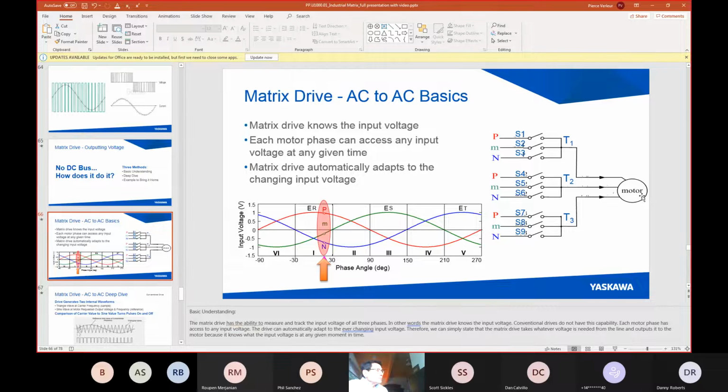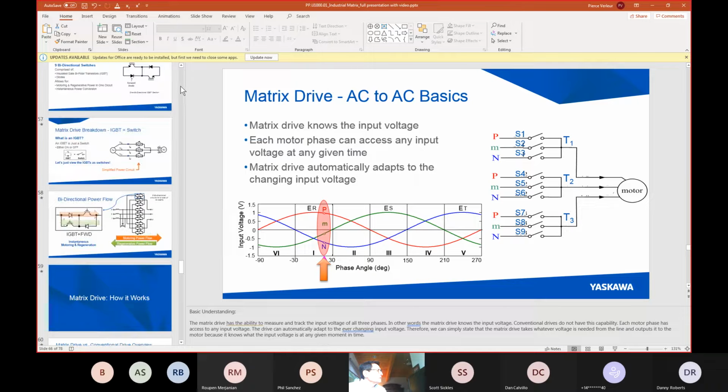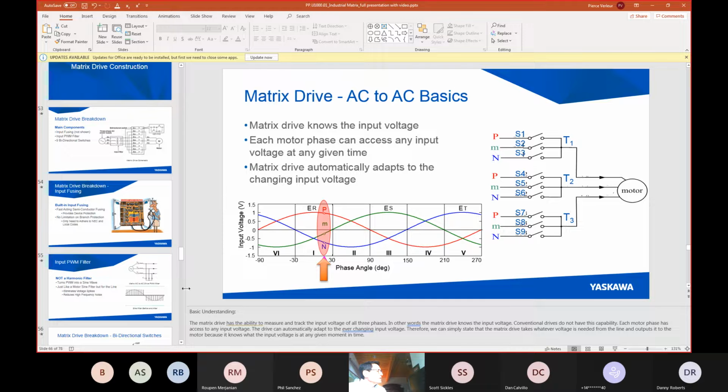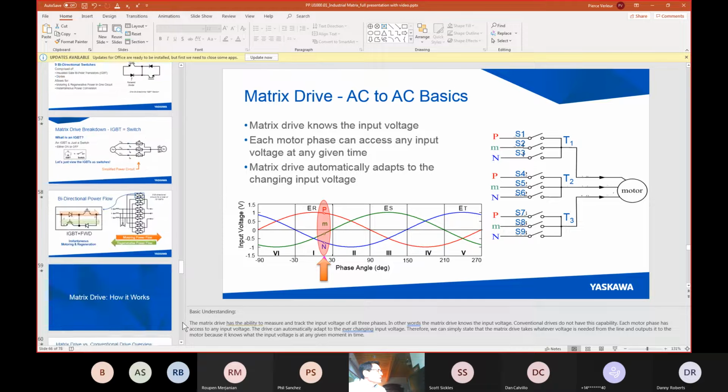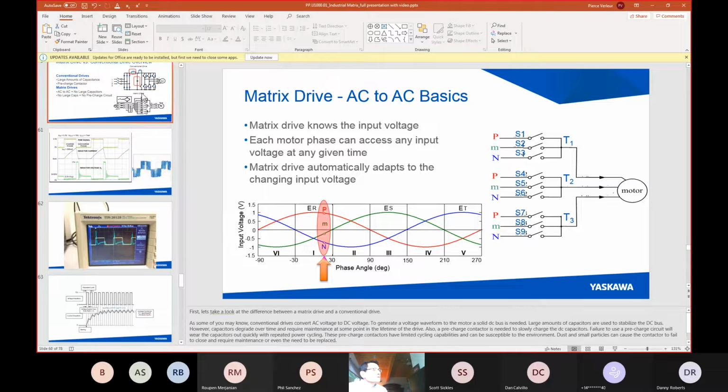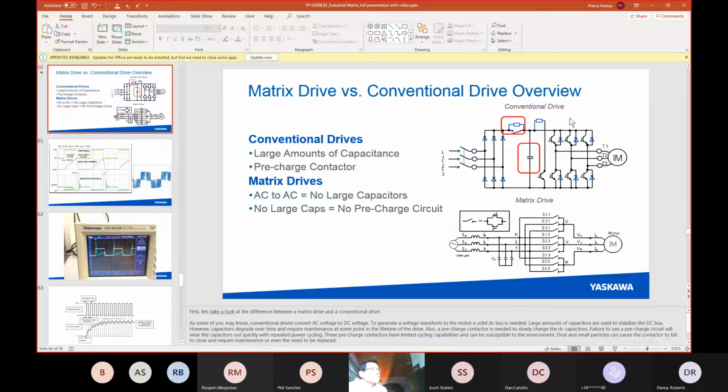And then with the simple 6 transistor H bridge of the PWM drive that we showed you earlier, the fact is that we could then switch using the limitations of our circuitry of the day and create nothing more than a control of on time and off time. Very simple to do. The initial VFD that did this in the United States market was the Toshiba VT130G1.